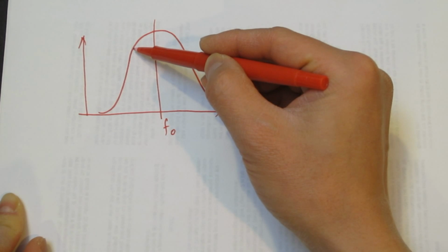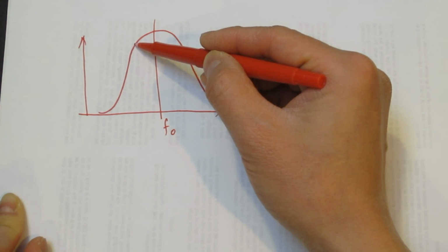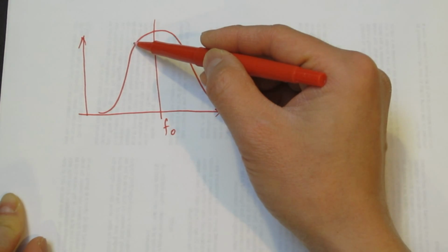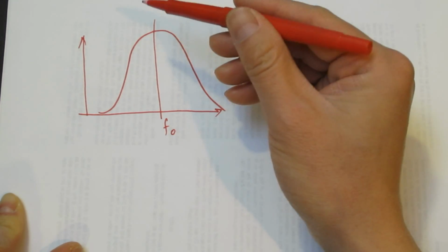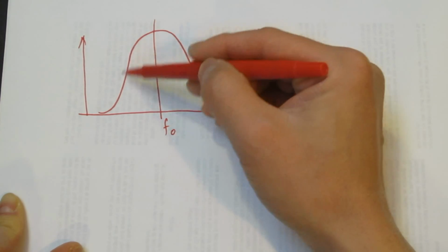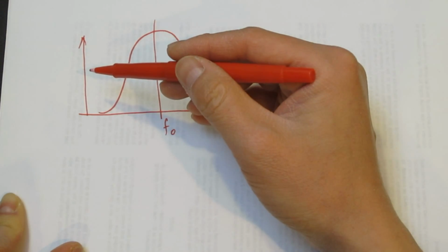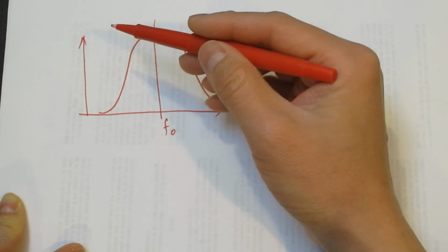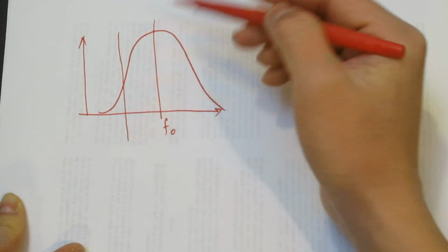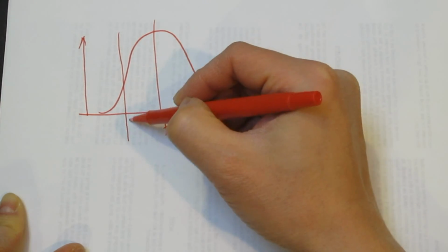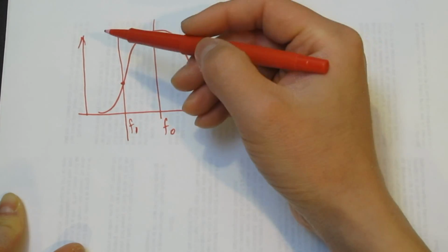If our signal sits at this frequency, then after passing through the bandwidth filter, the amplitude is going to be large because it's closer to the center frequency. So we utilize this slope of the transfer function of our bandpass filter to detect our FM signal. If we tune our zero span at, let's say, this frequency f1, then this is going to be your 0 point.